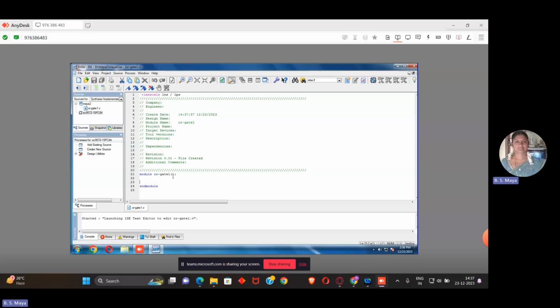I need to write a program here. Before that, the or and dash is a file name. I have to provide input output ports A, B, Y. Then you have to mention whether each is an input or output. Input is a keyword. A and B act as inputs. Output Y acts as an output.